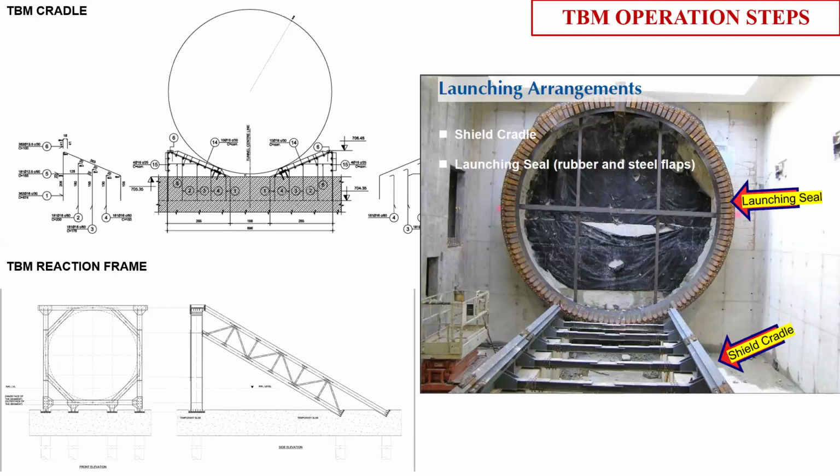In Lucknow we had three stations: Sachibalai, Hazratganj, Husainganj. We launched the TBM from Sachibalai, which is itself an underground station. The station is 120 or 100 meters long. We excavated only 30-40 meters of the shaft and supported it with a soldier pile wall. Once the TBM operation had started and the TBM had moved inside sufficiently, we started excavating the rest and made it a permanent shaft. I believe it is more difficult now when you are launching the TBM through a shaft.